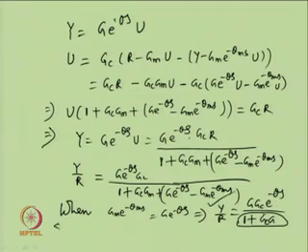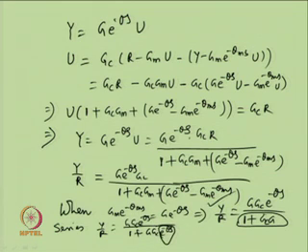Now, for the series feedback case, we get a transfer function of the form y upon r equal to G G_C e^(-θs) upon 1 + G G_C e^(-θs). So, this time delay term is not present in the closed loop transfer function of the Smith predictor and controller. This is the added advantage of the Smith predictor and controller that facilitates one to design a controller conveniently.